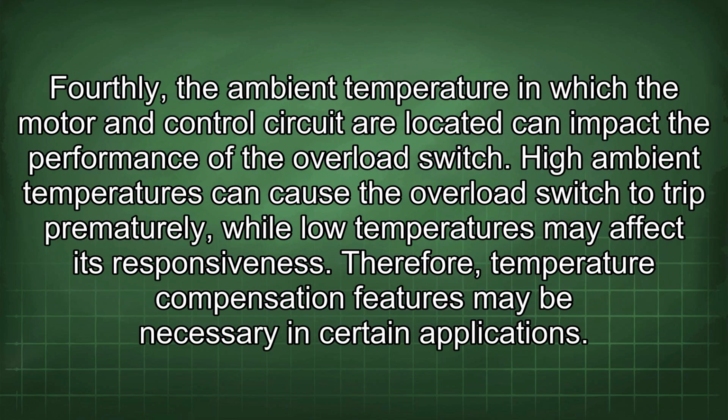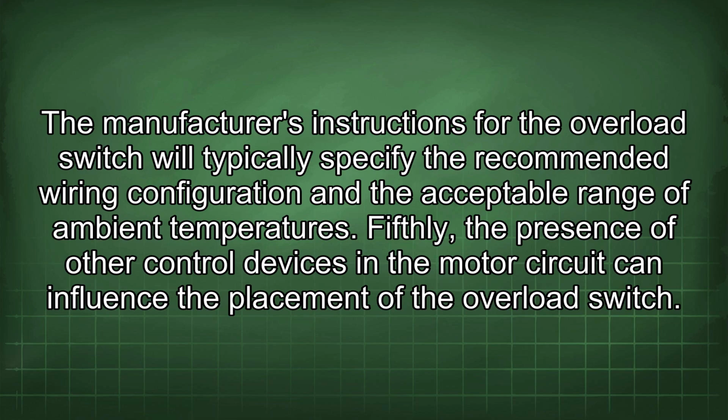Fourthly, the ambient temperature in which the motor and control circuit are located can impact the performance of the overload switch. High ambient temperatures can cause the overload switch to trip prematurely, while low temperatures may affect its responsiveness. Therefore, temperature compensation features may be necessary in certain applications. The manufacturer's instructions for the overload switch will typically specify the recommended wiring configuration and the acceptable range of ambient temperatures. Fifthly, the presence of other control devices in the motor circuit can influence the placement of the overload switch.